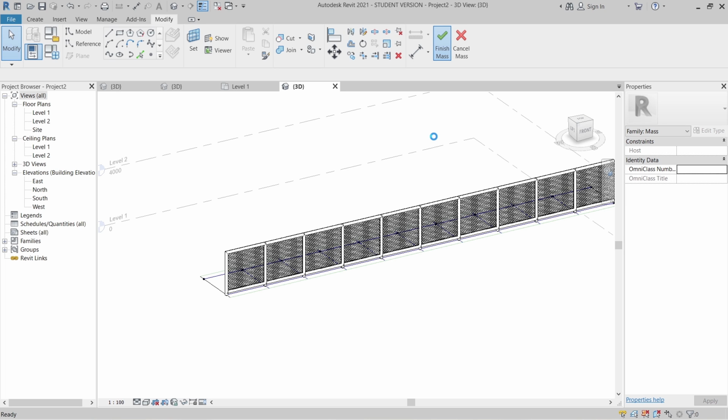Try to use texture. If using texture, it might be faster than that. And for texture, you don't need to go to Google and find that. You just simply go to the Revit library for WireMesh texture. It's also there. Just apply from that appearance library. Okay, just finish our mask. It also takes time, but after that your file will be running properly. Don't worry about that.